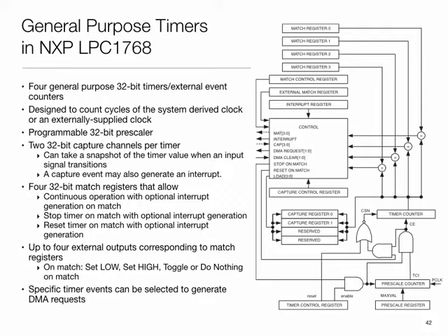There are so-called match registers, and the idea is that you set these registers to a value, and whenever the counter reaches that value, an interrupt is generated. So you can have the counter free running, and generate an interrupt at specific values. You can also have outputs going out, so you can have an interrupt being generated and outputs going out.